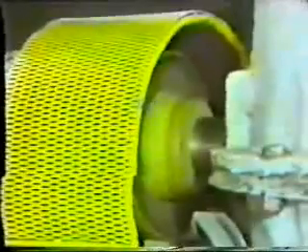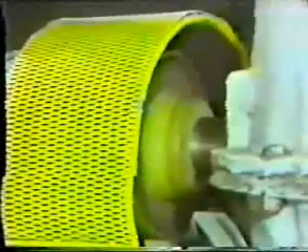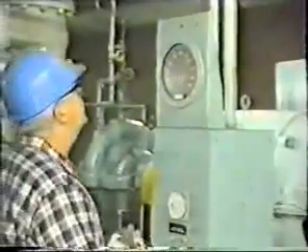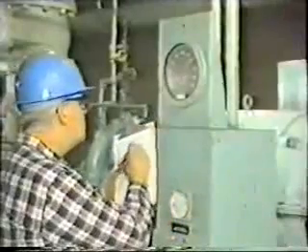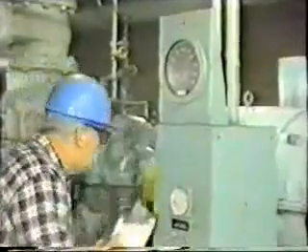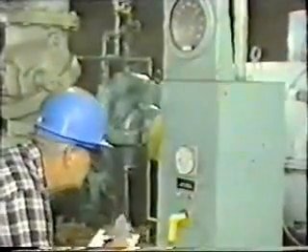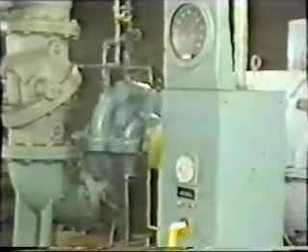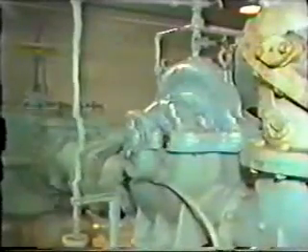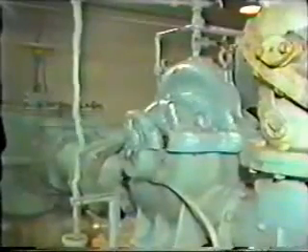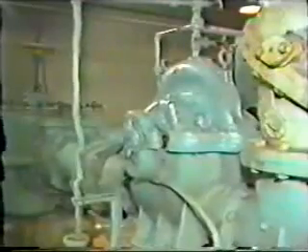Once you finish questioning the operator, you need to check other sources of information. As a troubleshooter, whenever possible, perform an operational check of the pump so you'll know firsthand exactly what the symptoms are. You may find clues about the cause of many problems in the indications on the gauges and recorders. Our gauges indicate that discharge pressure and running current are normal. For this particular problem, check the area around the bearings for evidence of lubricant having been forced past the seals. Overgreasing could result in overheating.